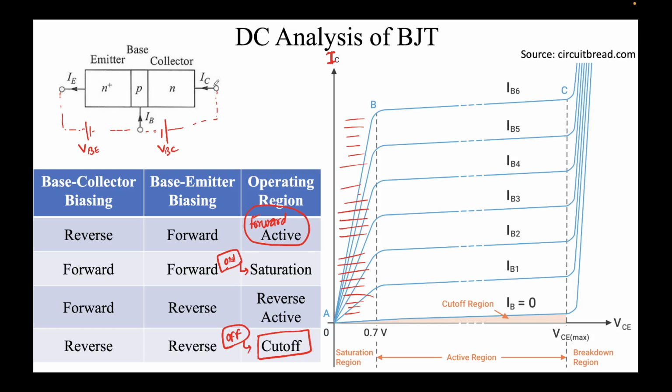So when we are operating in this saturation region, we can say the BJT is something like this, and this switch is closed if we operate in forward. Now you see only a resistance, which you are seeing over here. This value of resistance depends obviously on IB, for instance. It's not that the base is not playing any role, it's still playing some role. But this state is known as on.